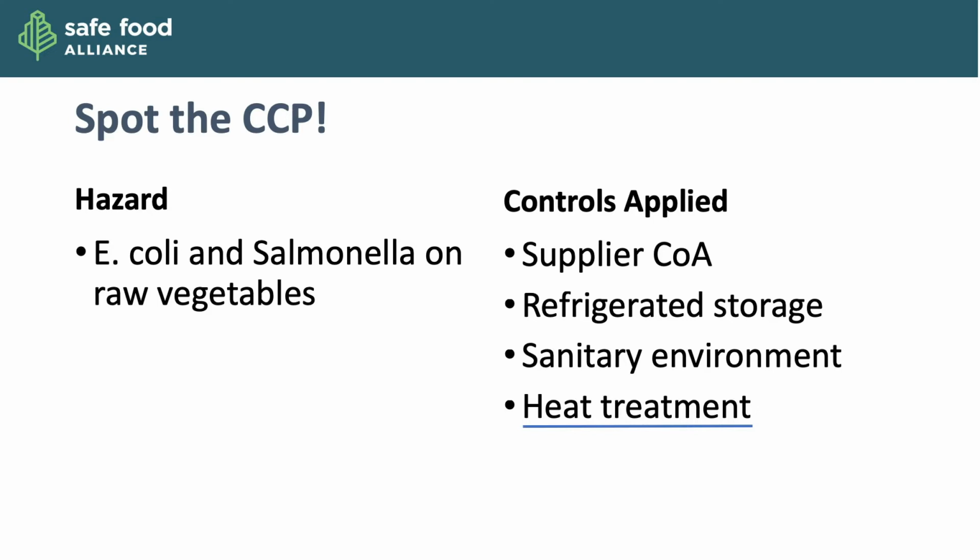So in this case, if it was something like a canning operation for those raw vegetables, or a freezing operation, or even a refrigeration operation, if you could blanch them or treat them up front, you're going to have a lot more success with controlling those hazards. And in this case, something like that kind of a treatment would be considered a type of pasteurization or a critical control point in its nature. So that's just one example of how critical control points can be determined.